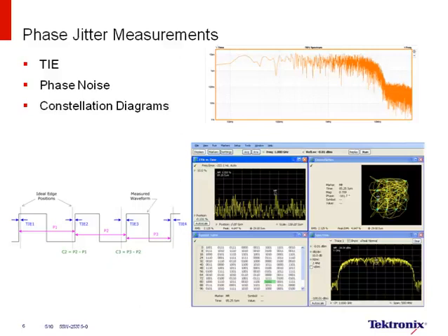No, because there is some likelihood that the receiver can actually equalize and open up the eye. So the other thing you want to know is, does the receiver have equalization? And if it does, you also want to equalize the eye before you make the measurements.